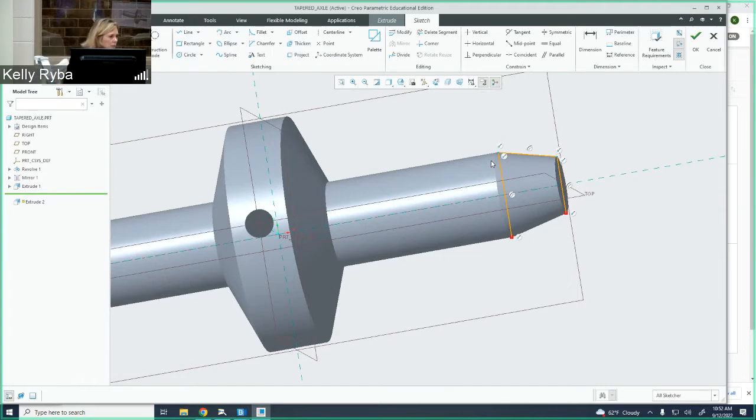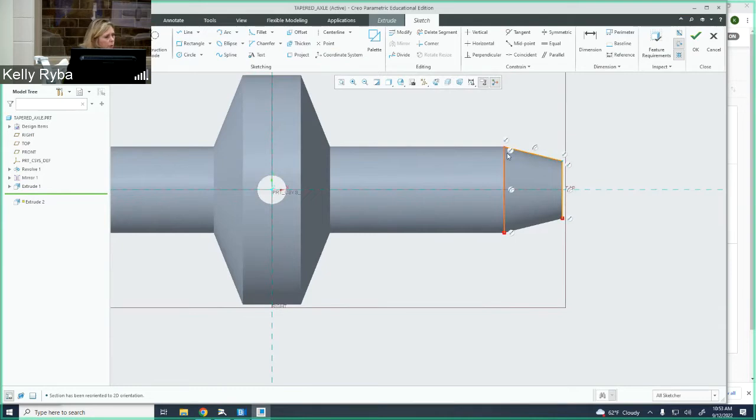Okay, that's why. So I'm going to get on my sketch plane again. Now my keyway is defined there as being 1/8 of an inch deep, and then it's going to be 1/4 inch wide. So the 1/8 of an inch deep is the offset that we're going to have here from this line to the bottom of the keyway. So I'm just going to add a line, and I'm just going to go a random depth like right here, and then I'm going to make sure, now notice that my constraint is parallel, and then I want it coincident over here. That way these two lines are parallel right there. I can middle mouse button to end. And then now it looks like I've got a dimension there. I didn't see it. This dimension, make sure that it's parallel.